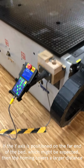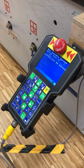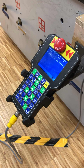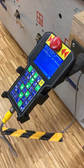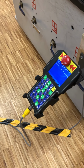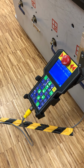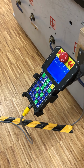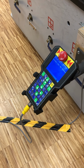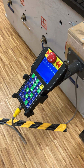And then you are always asked when you boot up, do you want to run the spindle warm-up using tool number what? The spindle warm-up is to make sure that the spindle, if it has been left unrun for a long time, actually I think it's 4 or 8 hours. One rule of thumb is that if it has been run previously in the day, you don't need to do a warm-up, but if you're running it for the first time during the day, then you do that one.